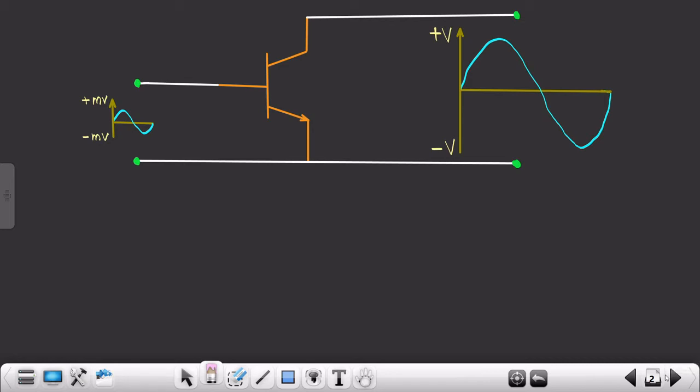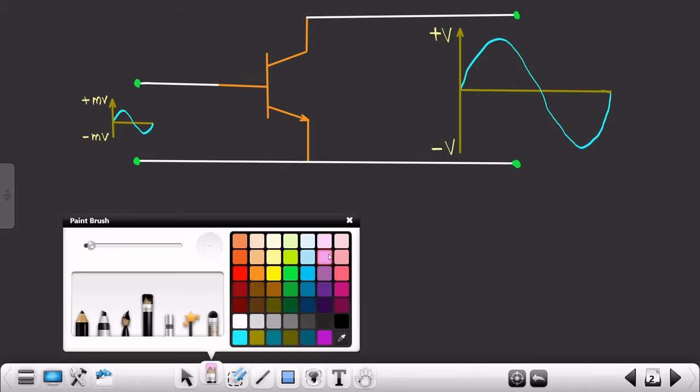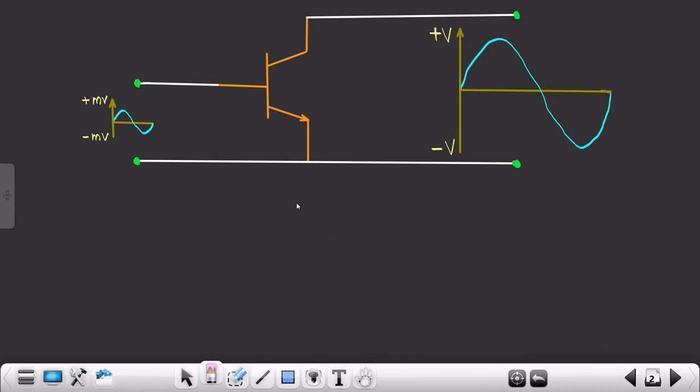The very first parameter involved is known as voltage gain. So we'll see what exactly it is. If you remember the third mini project, we had applied an audio signal to the input of the BJT, and at the output the LEDs were glowing on and off continuously. Remember that this audio signal is in millivolts. We amplified the audio signal, and due to this the LEDs were glowing on and off.